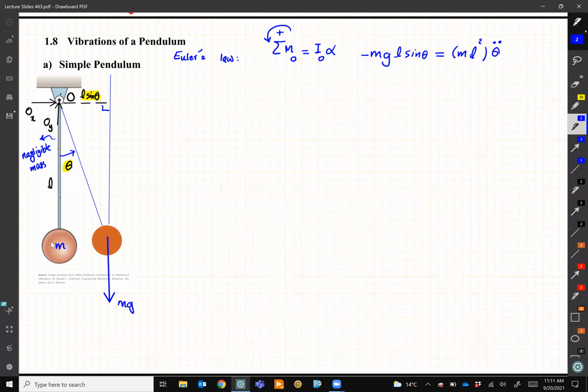So this is the equation of motion. Obviously, it is nonlinear, but we had a deal at the very beginning. We said in this course, variables are very small. It goes under the category of vibration, and that was the main difference between vibration and dynamics. If you go to a course like dynamics, MANU 265, for example, we assume large motion. So this pendulum goes maybe 60 degrees, but here in vibration, we assume this theta is in a range of 1 or 2 degrees. So with that deal, we can approximate sine theta and substitute it simply by theta, right? This is what we agreed. So if I simplify my equation, I get theta double dot plus, dividing everything by L, g over L times theta equal to 0.